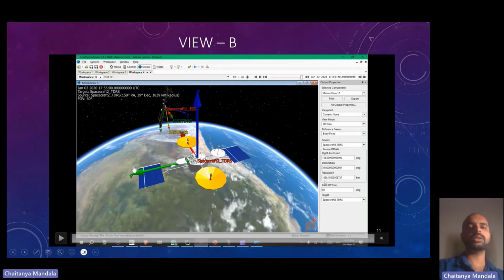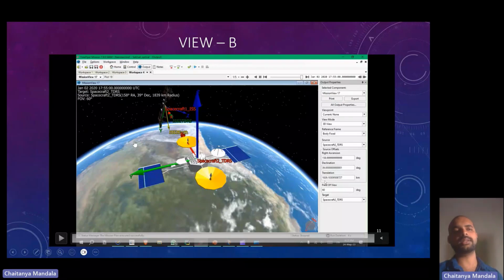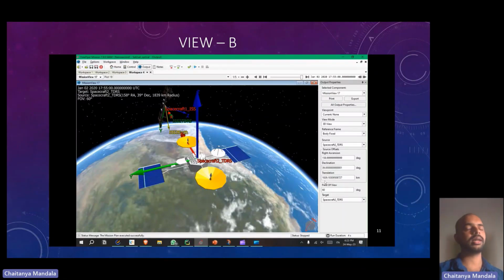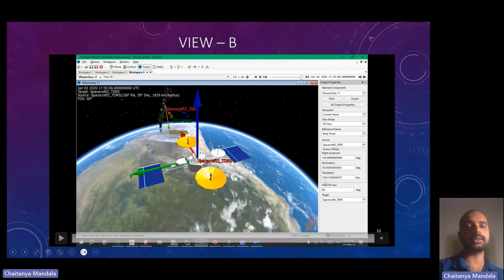All right, so that took about 1 day, as I said, but by changing the control parameters, after a bit of trial and error, with a ratio of KP over KD of 100, there are 2 parameters in control that I used, proportional and derivative. If the ratio was maintained at 100, then I could get the same 60-degree slew within 3 hours.